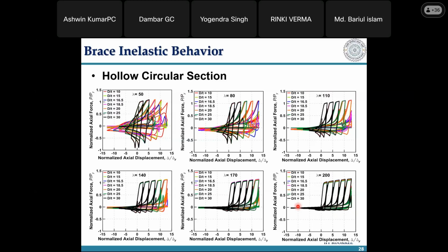If the earthquake comes in the opposite direction, the other brace will be in tension and the first one will be under compression. So you cannot give only a single brace, because if the earthquake happens in a cyclic way, it deforms laterally, and then the problem is that it will have no capacity. Once it buckles in compression, all the lateral force demand will go to the beams and columns, right? That you don't want.